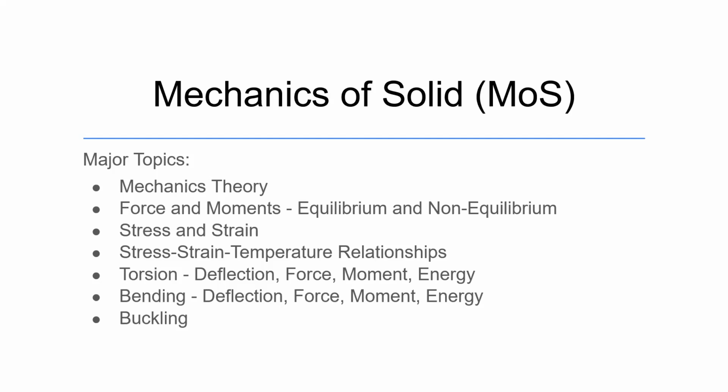But when we apply a torsional force, it is called a shaft, which is a cylinder. When we apply a longitudinal force and it bends, it is called a beam. And when we apply a compression force to the cylinder, to be correct, it is called a column, and it is undergoing buckling. So the same cylinder, when under torsion, is called a shaft; when under longitudinal force, it is called a beam; and when under compression, it is called a column. So three different names, three different forces for the same cylinder.